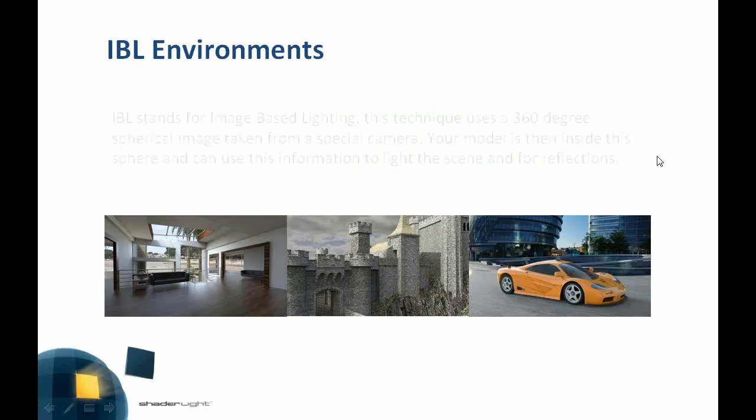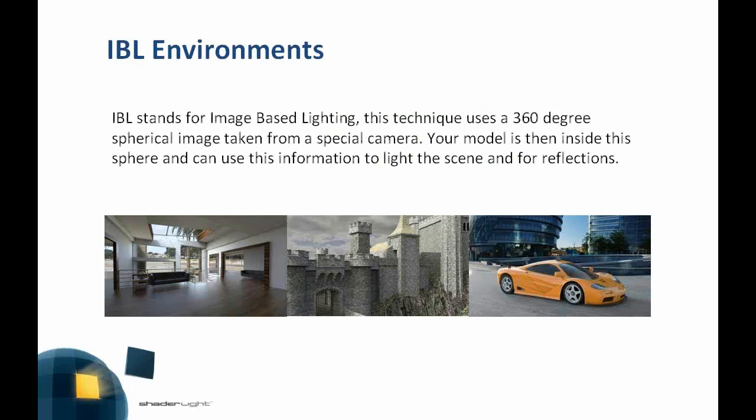Okay, so IBL. IBL stands for image-based lighting. Now this technique puts your model inside a 360-degree image. The image has a lot of special properties, and this enables you to light your scene, and it also provides real-world reflections that give your scene ultimately a lot of realism. We're going to look at what makes the IBL special, because a lot of questions we get on support are from people who use JPEG as a custom environment and don't get the results that they require. We're actually going to look technically at what the files actually do.